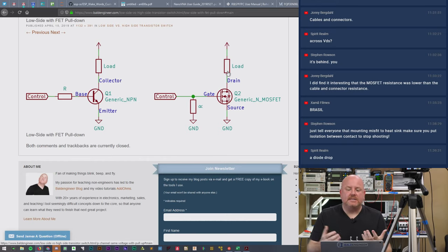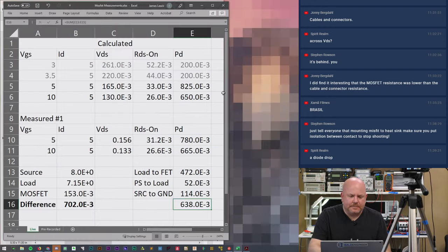Now earlier somebody did say, well, what if it was a real load and the load was changing? Well, then you're going to get a case where the voltage and the resistance of this thing is bouncing all over the place, but you can still sort of simulate what a real system would look like by simulating the worst case low, worst case high, and then average load current to get an idea of what's going to be dissipated on the transistor. There's more complicated methods, but it's there.